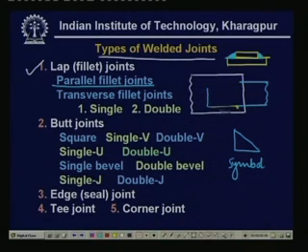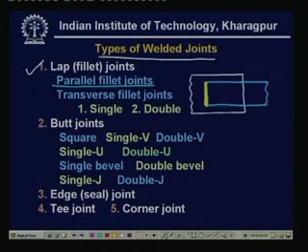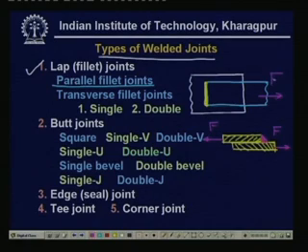Then of course, we could have used the welding in a different manner. We could have used the weld metal here. Then of course, if you look from the side, there is one metal and there is another. Now, here welding is applied here, so this part is welded. Of course, the force is given in this direction, force in that direction. So, the joint has to carry some load. So, load is acting here. So, this is known as the transverse fillet joint.